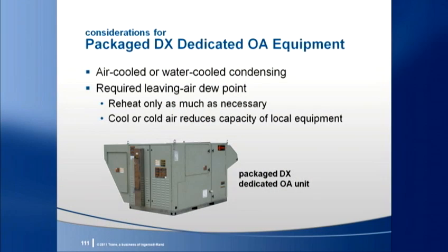This may require a higher level of control. The cost associated with the proper control of a dedicated outdoor air unit can be offset by limiting the use of reheat and taking credit for the sensible cooling provided by the outdoor air unit and downsizing the local equipment.